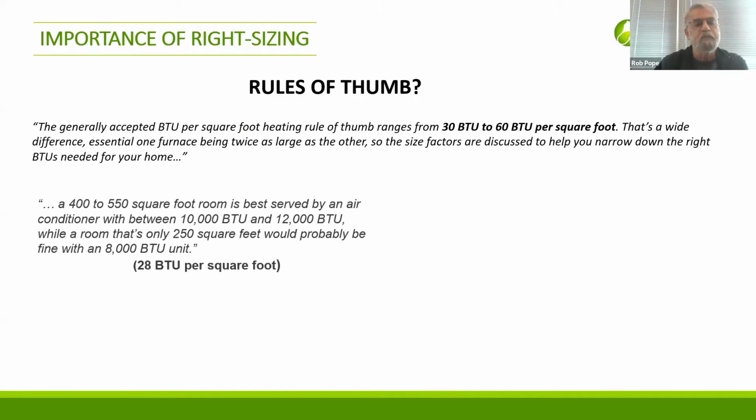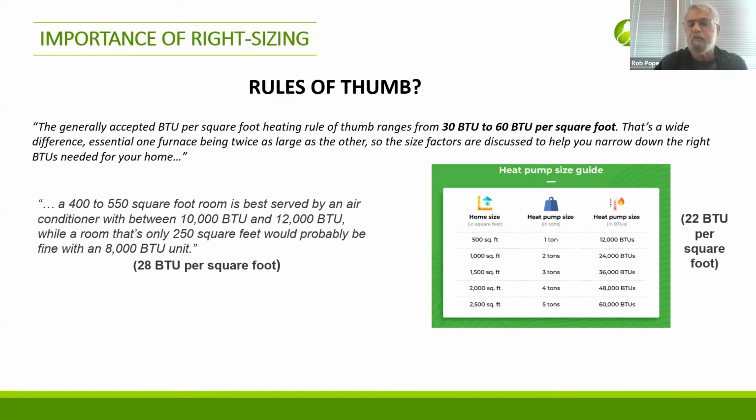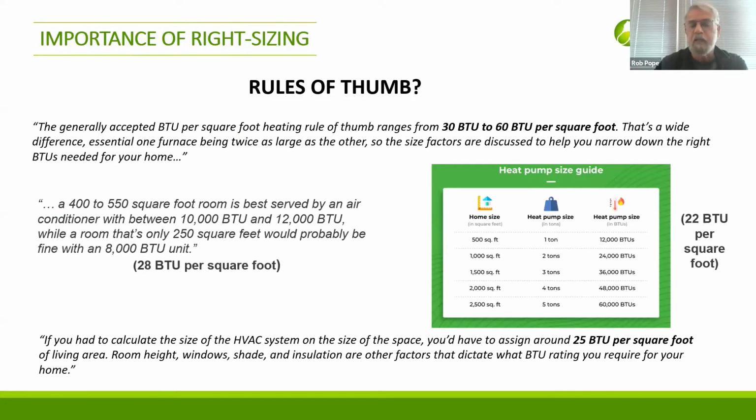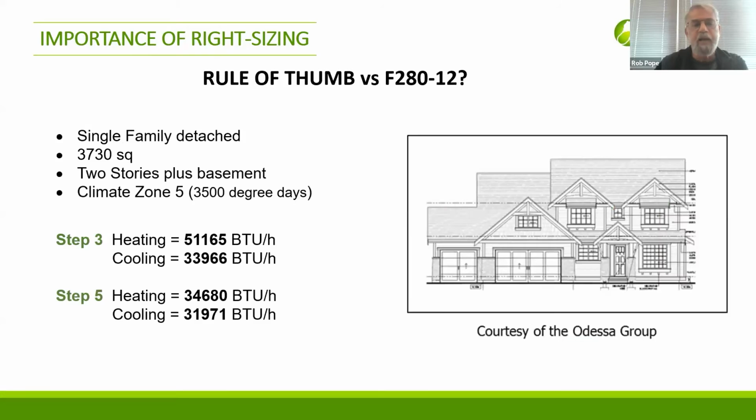Another, in the end, that ended up to be 28 BTUs per square foot. We saw another one, I think this one was 22. Let's see, we had 22 BTUs per square foot. And here 25 BTUs per square foot. Okay, so let's take that and see what happens.